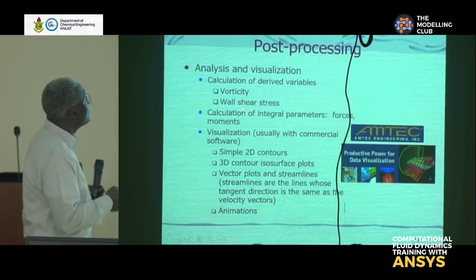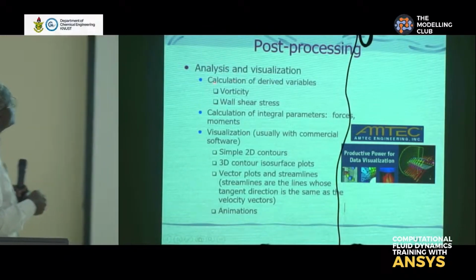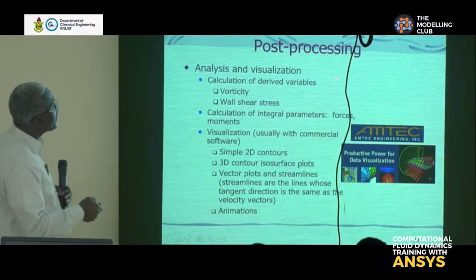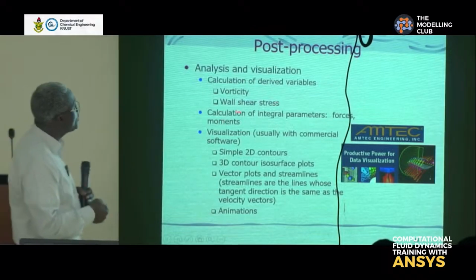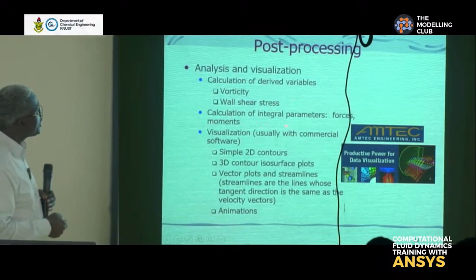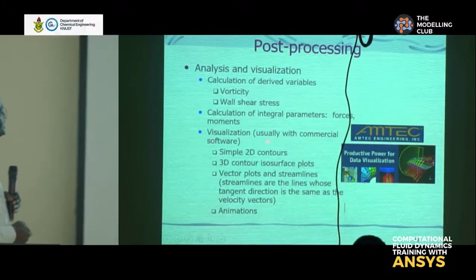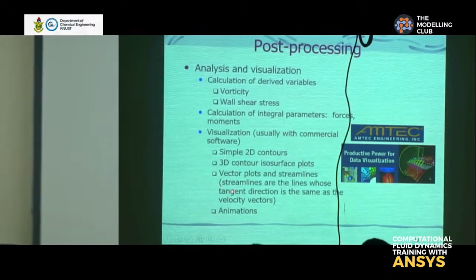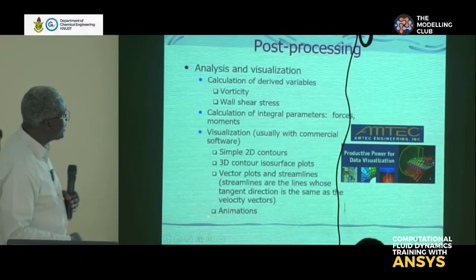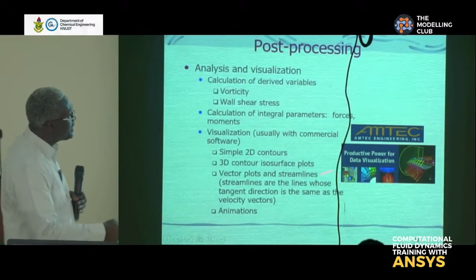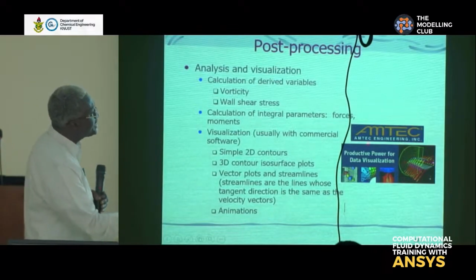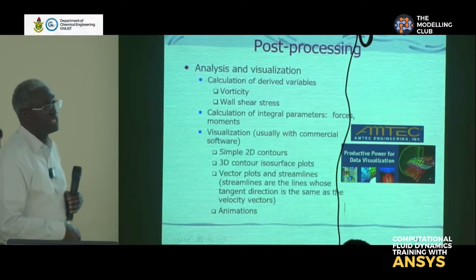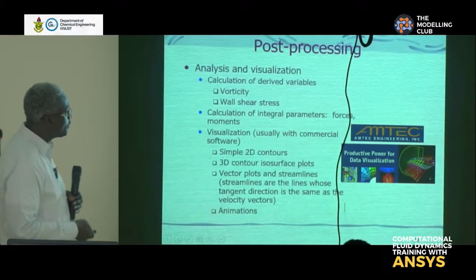For post-processing analysis, you have analysis and visualization, calculation of derived variables such as vorticity, wall shear stresses, calculation of integral parameters, forces and moments, visualization, usually with commercial software, simple 2D contours, 3D isosurface plots, vector plots and streamlines, and animations. There are various special softwares such as this Amtech that can give you that capability for generating nice plots for presentation, post-processing plots for presentation.